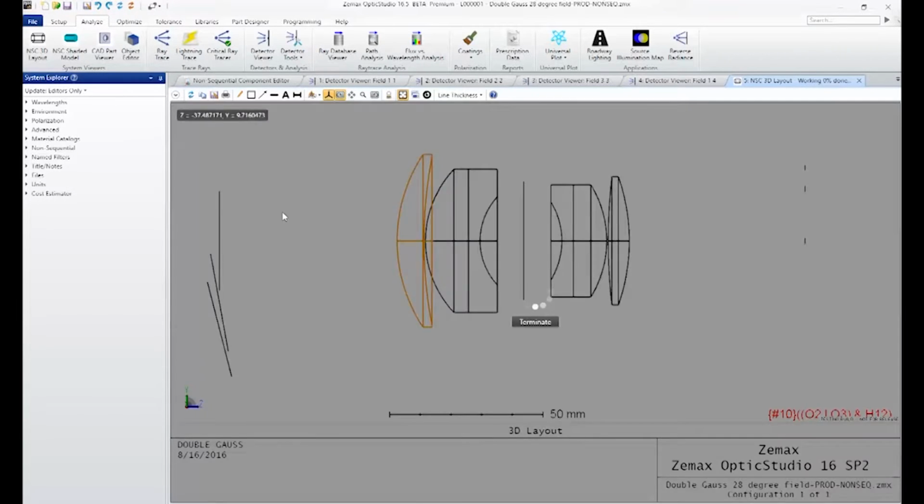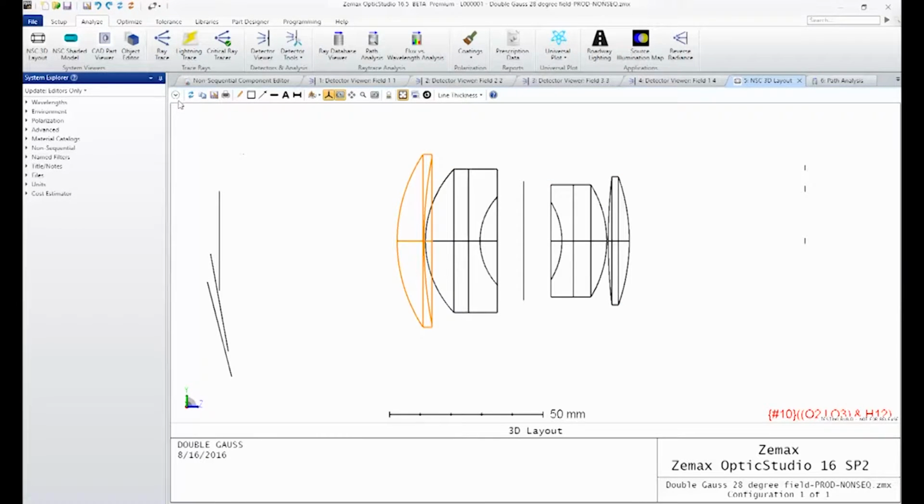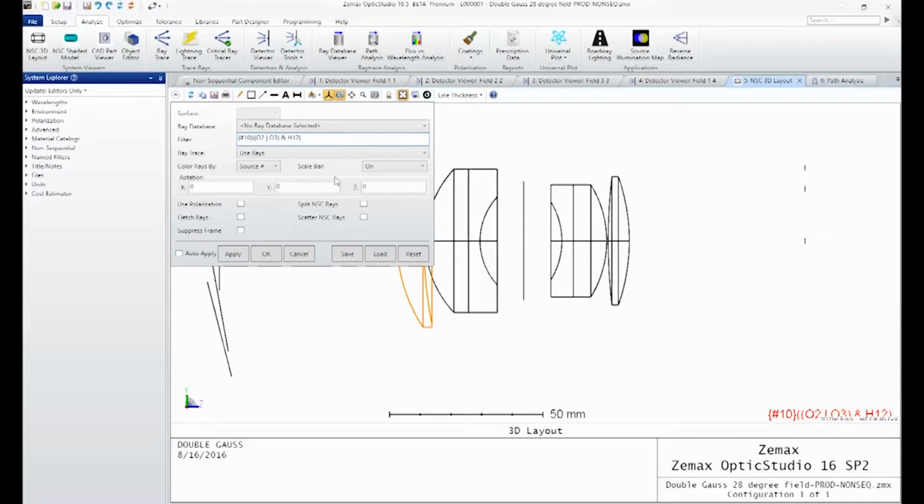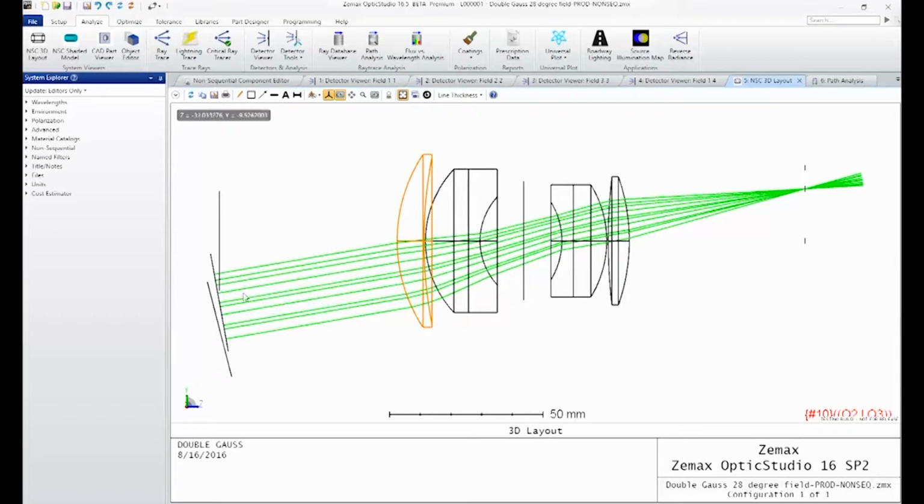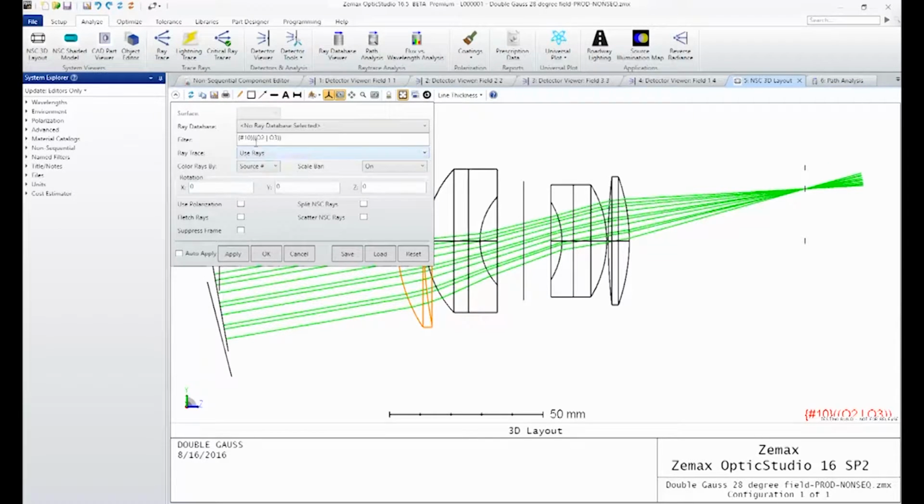And you can see in this case, for the 1,000 rays that we've selected, there aren't any that meet that particular string within the random set of rays that we've selected. We could certainly change the syntax just to illustrate the benefit. Now I'm just looking at 10 rays from either object 2 or object 3 that meet the first 10 rays that meet this filter string. So there are just 10 rays from object number 2 in this case. This can be combined with any type of filter syntax in order to generate a complex filter string, which allows you to selectively see a few rays that meet any particular filter string syntax.